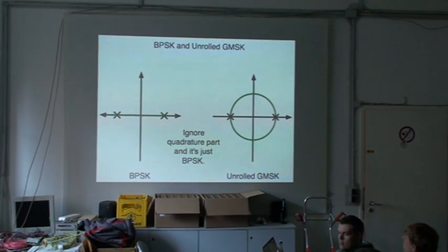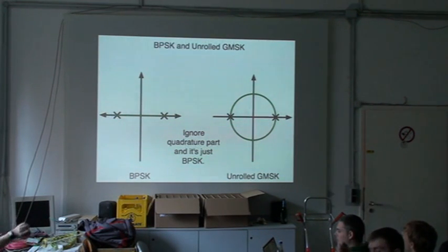I guess the reason I've taken, I don't know how much time I've taken to get through all this, 20 minutes maybe? 25, thank you. The reason I've gone down this long explanation is because a lot of people dig into the OpenBTS layer 1 and they're looking for things like phase lock loops and all this crazy stuff you see in the specification describing how to construct these signals. And that's not at all what's happening in there. What's happening in there is we're going to frequency shift the signal and just throw away the imaginary components.